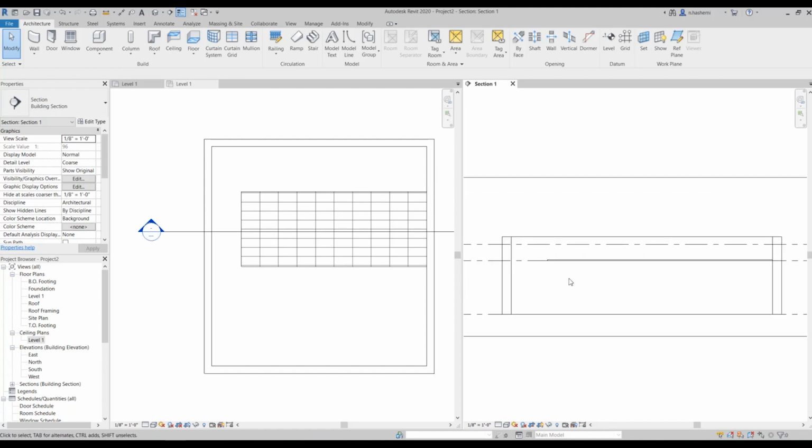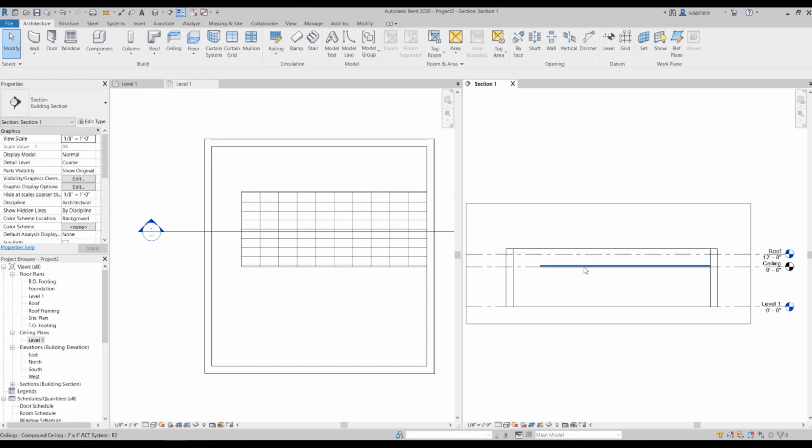Now, what if I have ceilings in different heights? Even if you have ceilings that are a little bit off of this level, you can set offsets from this level, in instance properties. This way, all your ceilings around it will be tied to this ceiling level. So, for example, I want to have a ceiling here, which is 9" above this one, 9" higher than this one.